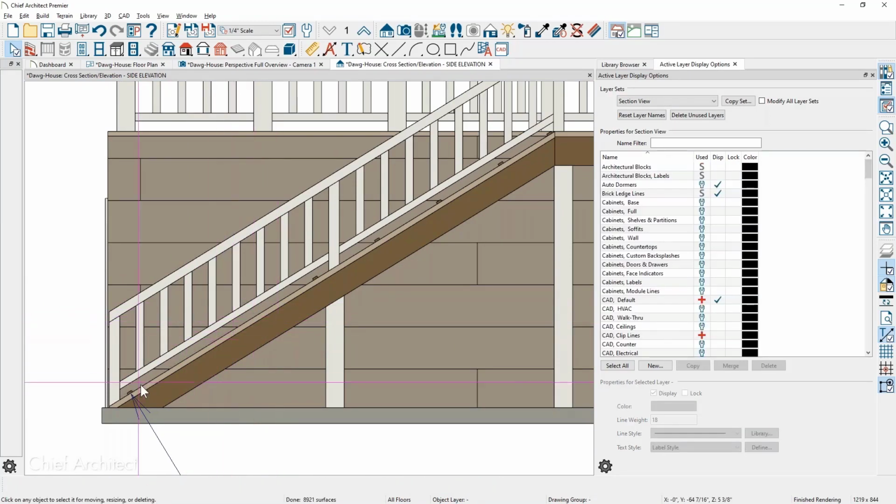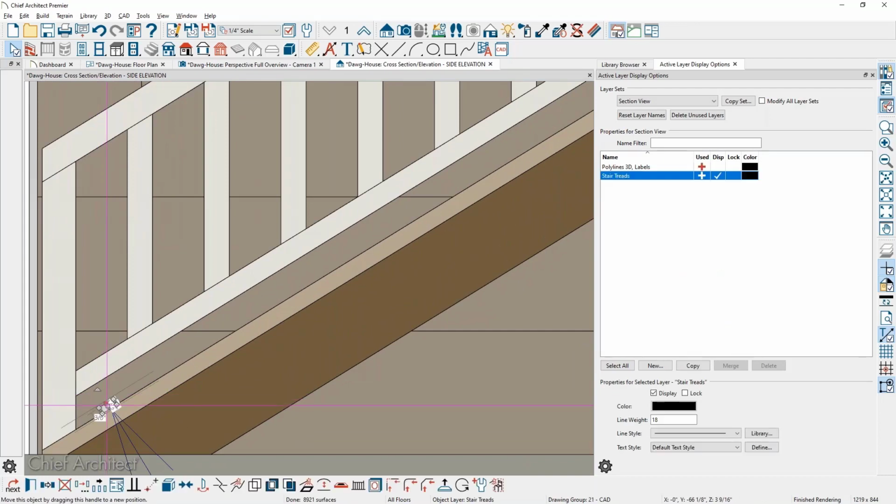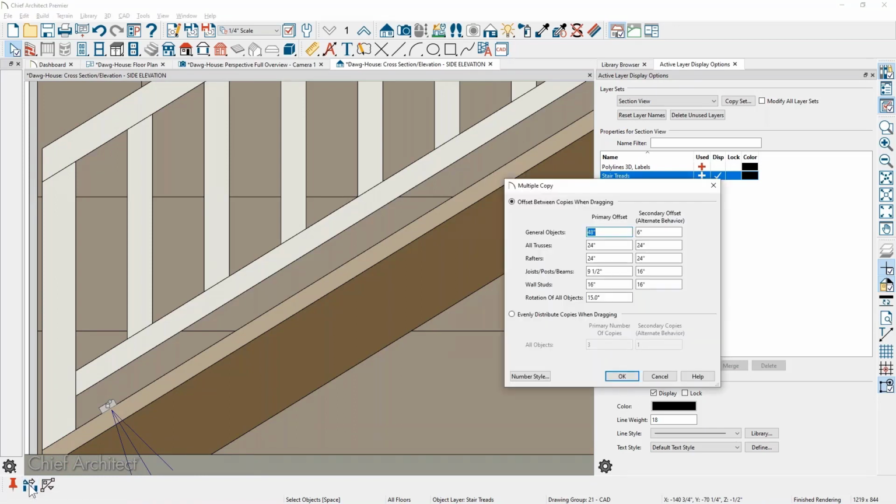I'm not going to delete all of them, but what I did was once I selected the traction strip, use the multiple copy key, which is down here in my lower menu system. And I'll pause there for a minute so you can see that. And once I have it selected, then I'm going to use this setting for controlling the multiple copy interval. So that's, again, in the lower left-hand section of my screen. Once you choose that, I use the evenly distribute, and you can set the number of objects. In this case, it's 3.